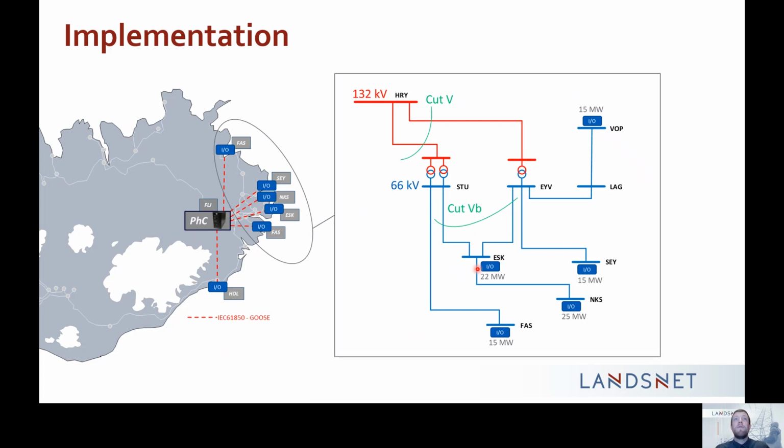There we have implemented one regional Phasor controller, which we implement with GOOSE communication down to these different locations, and we trigger the load shed really fast, at least compared to the old way we did it only with frequency protections, where we always had to wait until the event became really bad to start tripping load. Now we can detect it with these wide area controls really early in the stage and trip it way before it reaches some critical levels, for example, in the frequency.